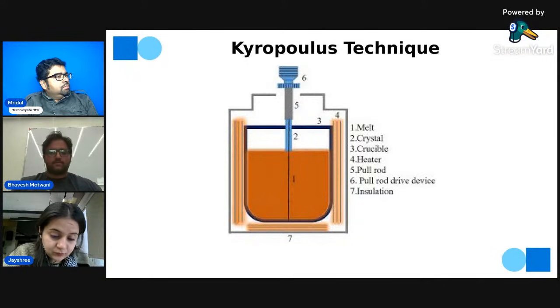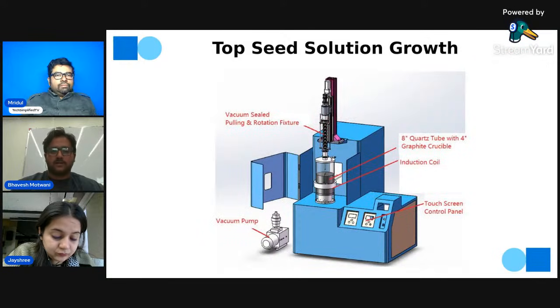And for the cooling, it is taken out slowly. For the thermal budget, we don't drop the temperature at a huge pace. We reduce it by 1 degree Celsius at a time, or even lower than that, such that we can cool it properly and there are no density defects, pores or holes inside.